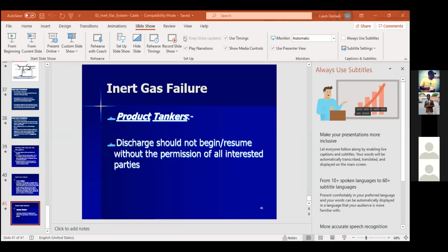What we are discussing here is strictly a requirement by SOLAS. So most of those are non-SOLAS. For instance, if you have a warship that is carrying fuel, it doesn't have to comply with SOLAS, because the application of SOLAS does not extend to warships, wooden craft, and some sort of pleasure craft. So even if those are carrying crude oil, they don't have to comply, because this is strictly a SOLAS requirement. They might just put additional safety measures. They don't even have some lines as well, so they don't comply with a lot of stuff.